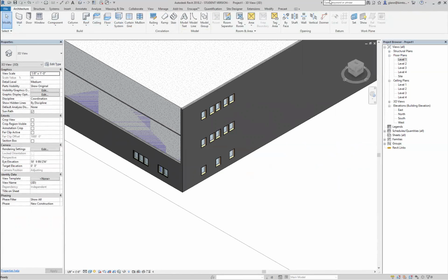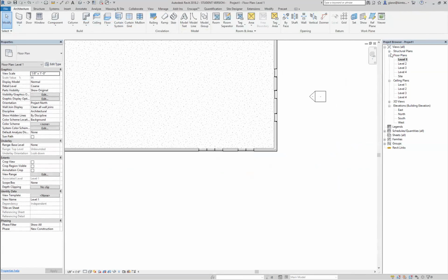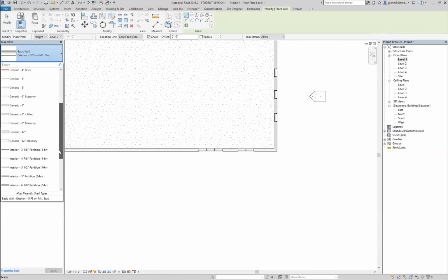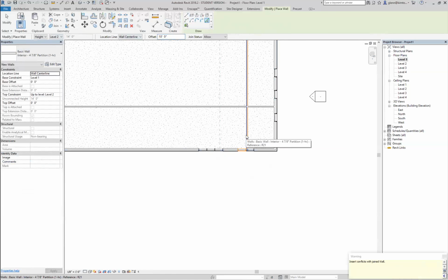Let's go through and draw just a few interior walls. Again, as you're starting to work, you probably have some sort of a hallway that's at some specific distance. So let me put a nice interior wall here. I'm going to say, and this is a very useful technique, you can pick a wall and offset it. I'll make it 16 feet back. Then I can think about creating the offices in the other direction. Maybe those are all going to be 10 feet wide. So I can say 10 feet over, 10 feet over,